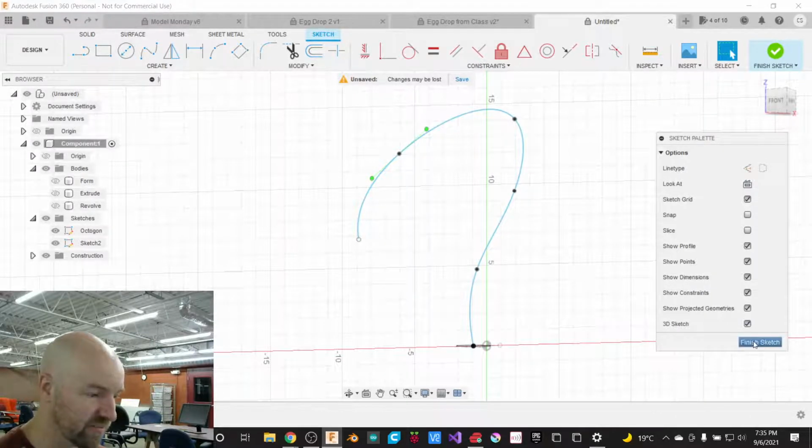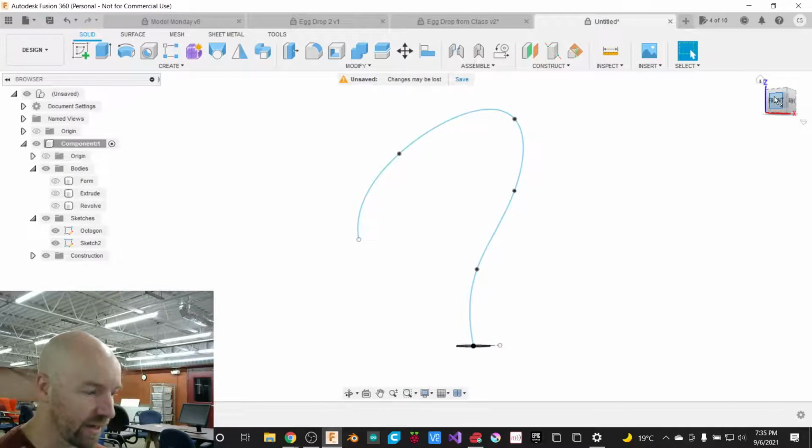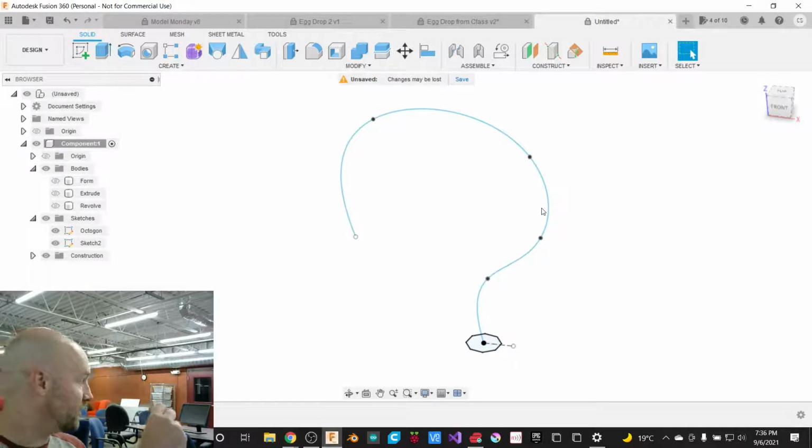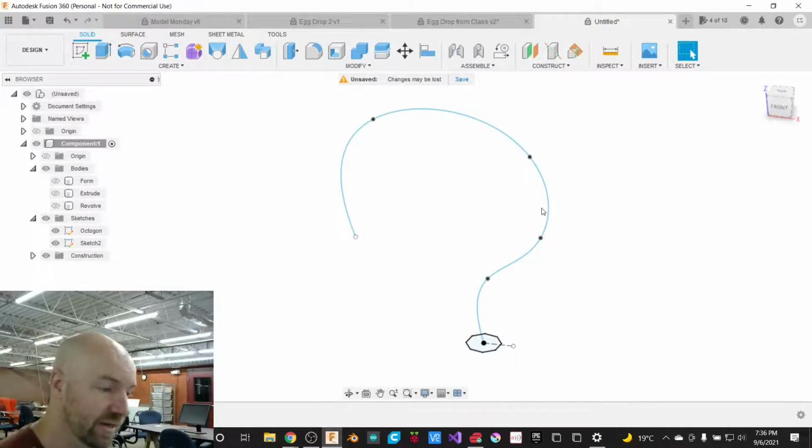I'm going to go ahead and click Finish Sketch here. And I'll want to model all my wires, because wires take up a lot more space on the inside of a little box than you think they do, right? Yep. And so sometimes I'll model the wires. Sometimes I'll even kink the wire and then measure how much of a curve I can make out of this wire, out of my solid core, or whatever it is. And then I'll make sure that I have those kind of constraints built into my sketch here.